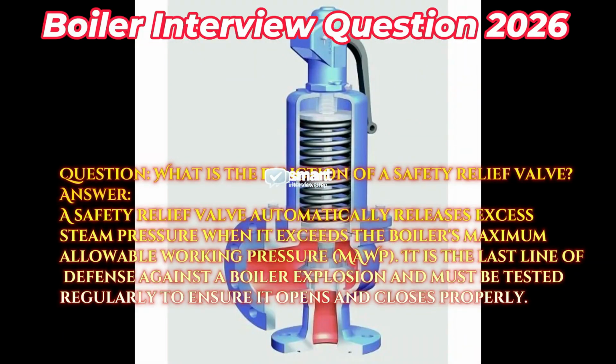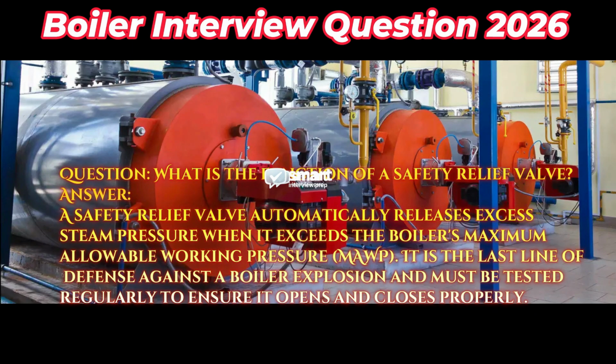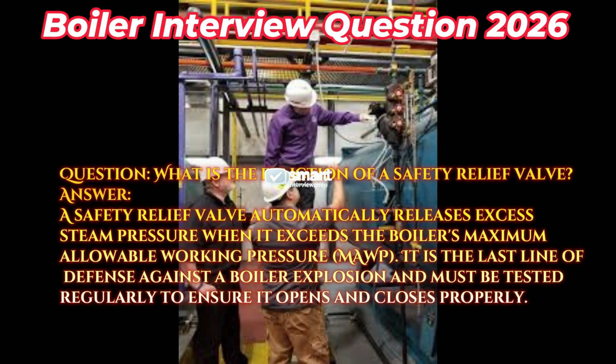Question: what is the function of a safety relief valve? Answer: a safety relief valve automatically releases excess steam pressure when it exceeds the boiler's maximum allowable working pressure, MAWP. It is the last line of defense against a boiler explosion and must be tested regularly to ensure it opens